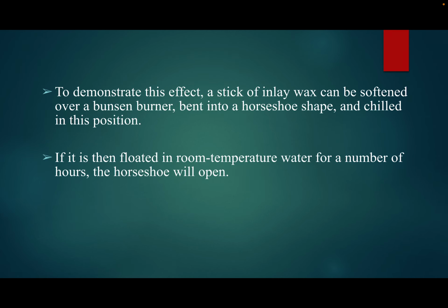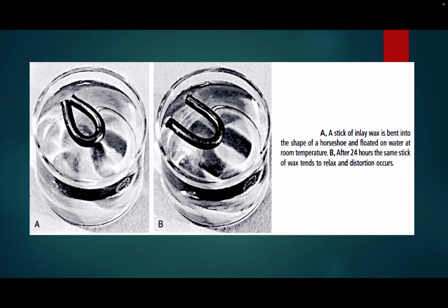elastic memory. To demonstrate this effect, a stick of inlay wax can be softened over a Bunsen burner, bent into a horseshoe shape and chilled in this position. If it is then floated in room temperature water for a number of hours, the horseshoe will open. Here we can see that a stick of inlay wax is bent into the shape of a horseshoe and floated on water at room temperature, and after 24 hours, the same stick of wax tends to relax and